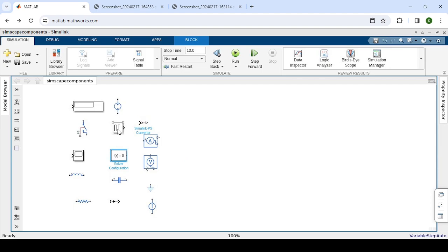We have this pulse generator. You can double tap on it. More on that later, by the way. We'll talk more on the pulse generator later, but we're going to use it to control this switch here, because the pulse generator outputs a physical signal, so we can mimic the effect of a switch being closed or open.